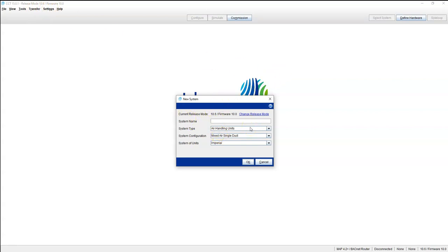You said basic, so let's just do a basic VAV box. Okay. So we have to give the system a name. I suggest naming it not VAV01, VAV02, VAV03, right? This is a generic system name. So say your VAV has SCR heat, you would name it VAV underscore SCR. That way it gives it kind of a description, right? If it has two-stage heat, VAV 2 STG HTG. There you go. Okay. So we'll go with two-stage heat.